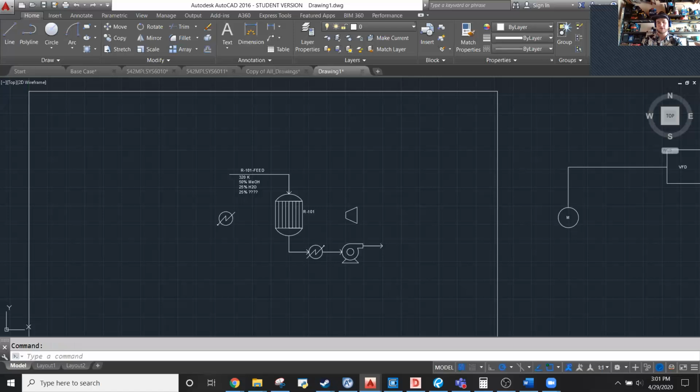You're going to have a contact on your rung that is your output that turns on the light. So when you hit that button to close the normally open contact, it energizes the output, which feeds into the circuit that energizes the output. It keeps itself energized until you break the circuit. So that's your verbal description. I'll write that in the homework assignment, but if I draw it, it'll be super obvious how to program it and you won't have to think about it at all.